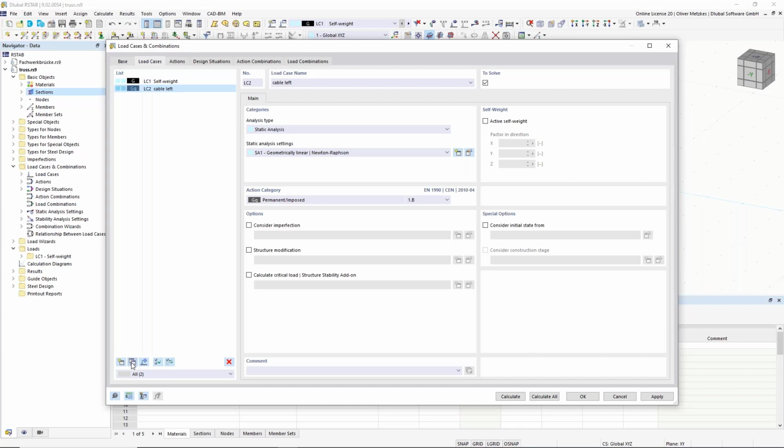And I also want to have another one where I also have cables at the right side, additionally. So I want to say that I only can have cables on the right side if I already have them on the left side, because otherwise, if I don't have them on the right side, I want to have another load case, which would be a walkway. So if there are no cables at the right side, you can also walk at this side. So just to have some alternative that we can see how we can handle later in the combinatorics.